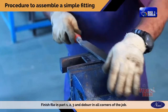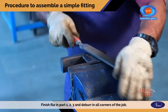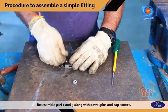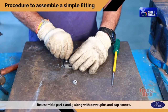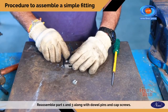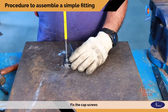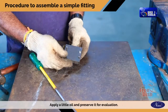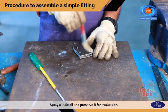Finish file in part 1, 2, 3 and deburr in all corners of the job. Reassemble part 1 and 3 along with dowel pins and cap screws. Fix the cap screws. Fit part 2 in part 1 and 3 opening slot. Apply a little oil and preserve it for evaluation.